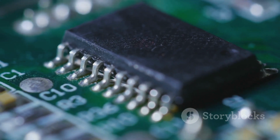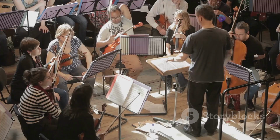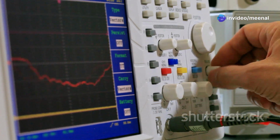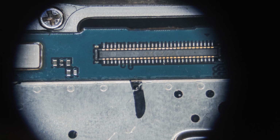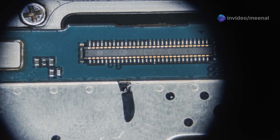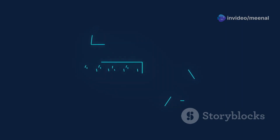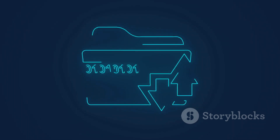MOSI, master out, slave in. This is the line where the master sends data to the slave. It's like the conductor giving instructions to a musician. Data travels one bit at a time, synchronized with the SCK signal. MISO, master in, slave out. As the name suggests, this line is for the slave to send data back to the master. It's the musician responding to the conductor's instructions. Data flows in the opposite direction to MOSI, also synchronized with the SCK signal.